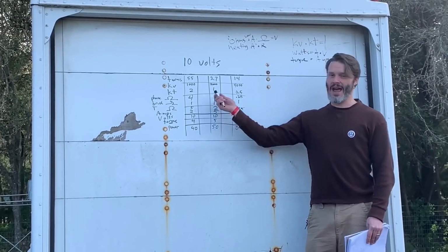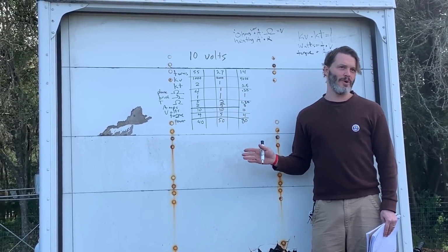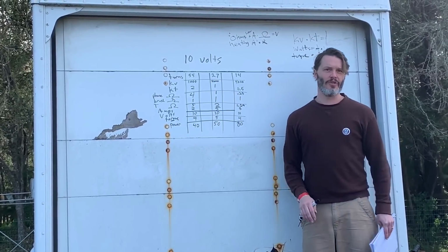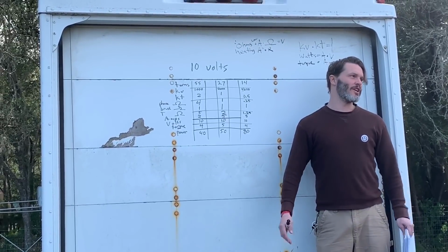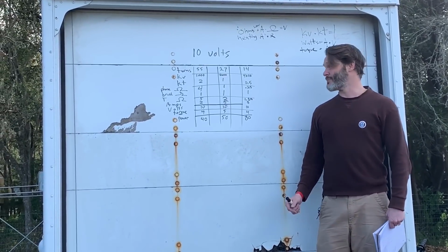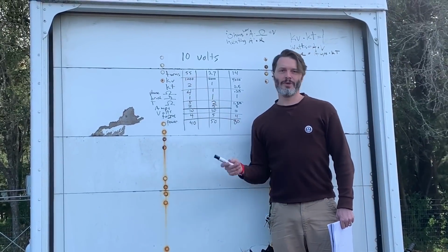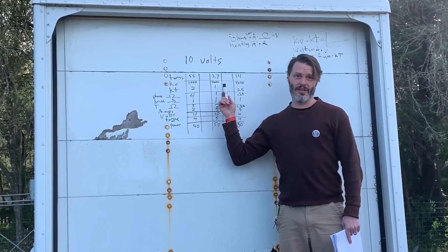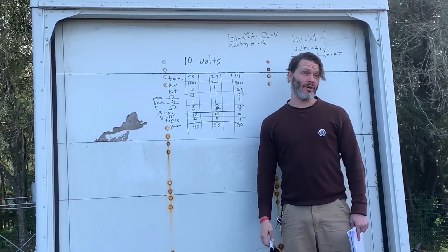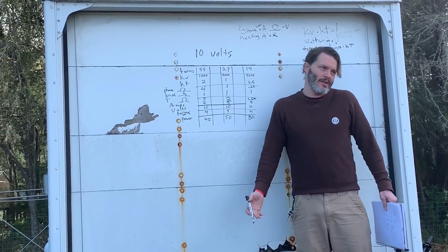But as far as having that golden zone move, I don't know if anybody could actually perceive a couple of turns here or there. That's more of esoteric stuff at this point. So let's even this up a little bit. Our 55 turn motor is going to be spinning at half the speed of our 27, so it's going to be making a lot less power on top of everything else. It's going to be kind of a poofy motor.